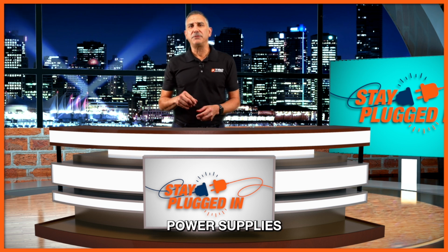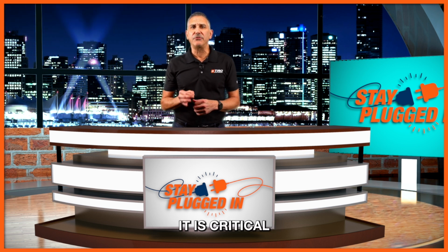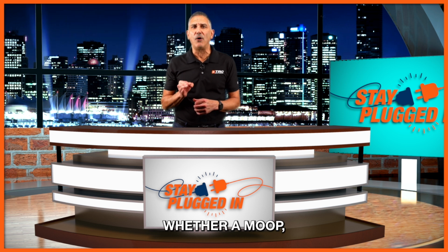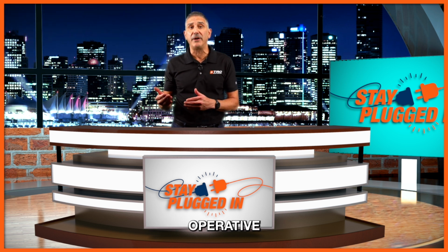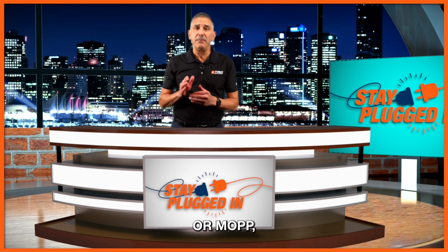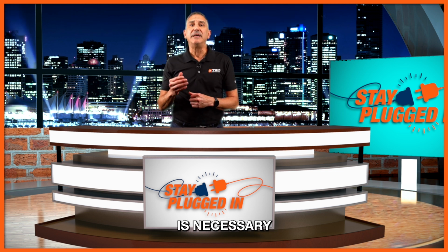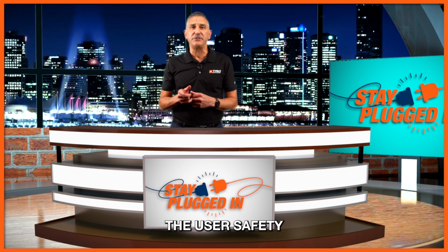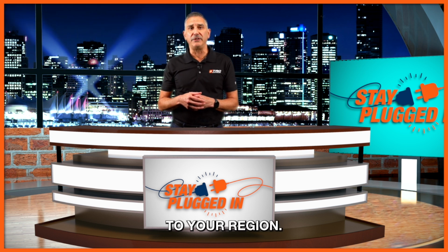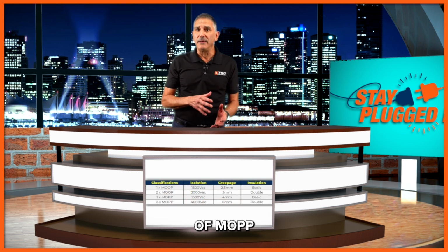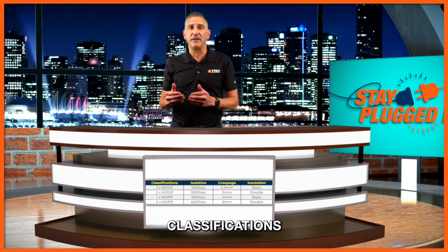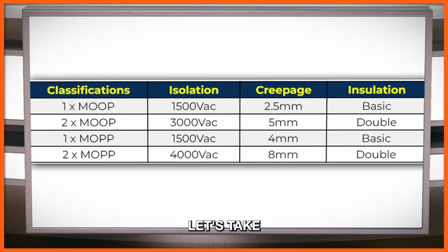When selecting power supplies for medical applications, it is critical to understand whether a MOOP, which means Means of Operator Protection, or MOPP, which means Means of Patient Protection classification, is necessary for ensuring the user's safety and compliance to your region. Now, here's a general overview of MOPP and MOOP classification levels. Let's take a look at how you can discern which means of protection classification to start with.